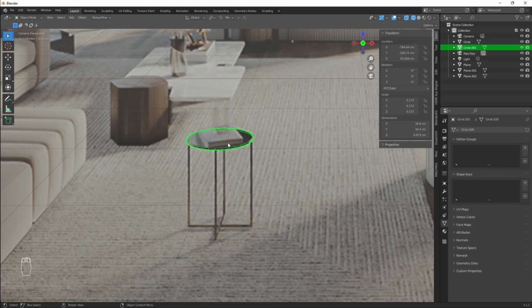As you know, Blender adds new objects at the cursor position. So I can click here and then drag the cursor with my mouse. But the best thing is that the control snapping I've just presented works in this mode as well. So if you have the snapping target set to face, you can put your cursor onto any surface right away. And although from this view it's not that apparent, it will be well pronounced in the 3D view, so let